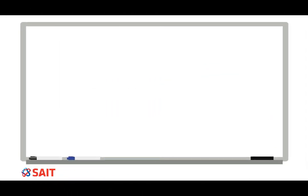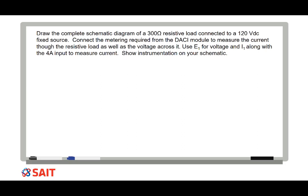In order to draw a schematic diagram from a description, you first need to make sure you use the correct schematic symbols to represent the circuit components you need to draw. Let's do an example similar to the first circuit you draw in lab number 1. Here the description says, draw the complete schematic diagram of a 300 ohm resistive load connected to a 120 volt DC fixed source. Connect the metering required from the DACI module to measure the current through the resistive load as well as the voltage across it. Use E1 for voltage and I1 along with the 4 amp input to measure current. Show instrumentation on your schematic.